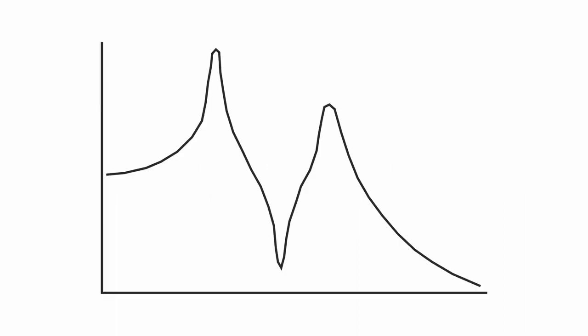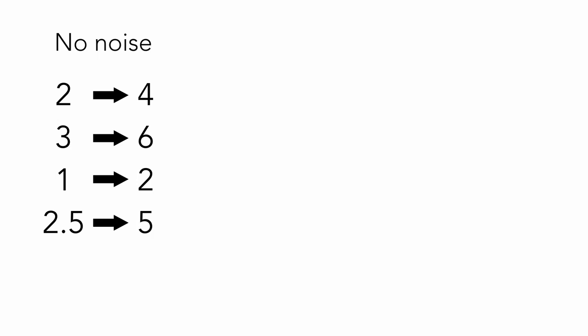Let's suppose some FRF measurement. On the graph is the theoretical accurate FRF function. We can see 2 resonances and 1 anti-resonance. In real situation, every signal contains the noise, and it distorts the results. We can suppose the noise on the input or on the output.